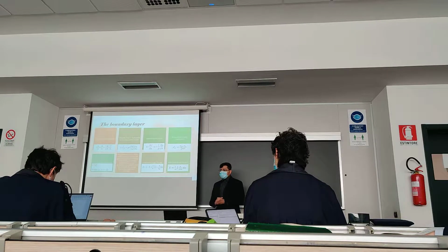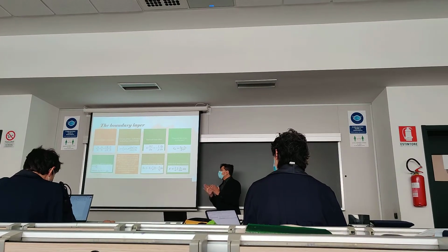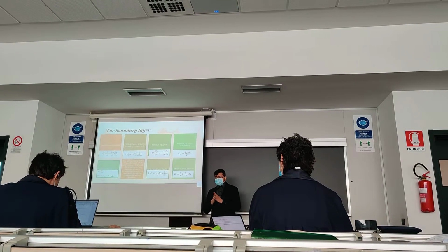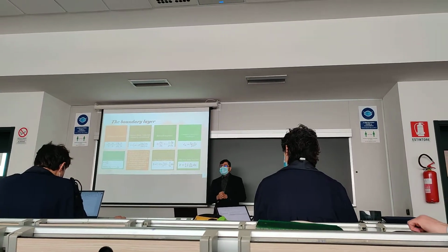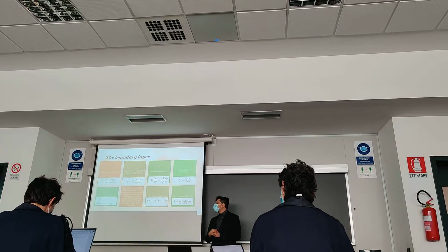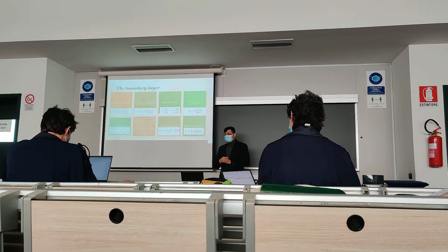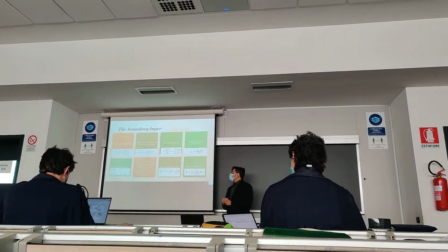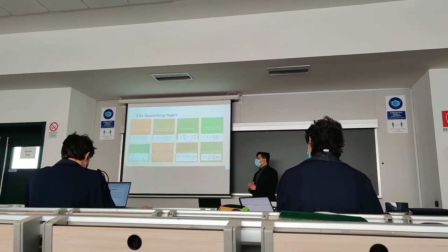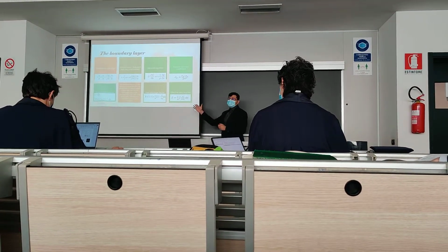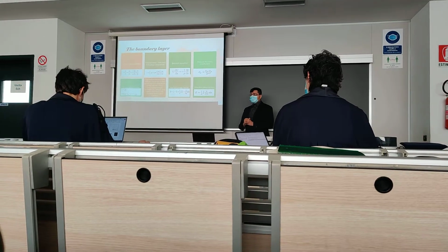Okay, and geometrically speaking, the diffuser has many geometrical parameters, but the main geometrical parameters which affect its performance are the passage divergence, the approach length, and the area ratio. The velocity component and inlet airflow also contribute a little bit. So the Reynolds number and Mach number of the air also contribute, but those contributions are small. And the typical geometrical feature which we have to reduce in order to control the boundary layer and increase the efficiency of the diffuser is the inlet blockage factor. So this inlet blockage factor, we have to reduce it.